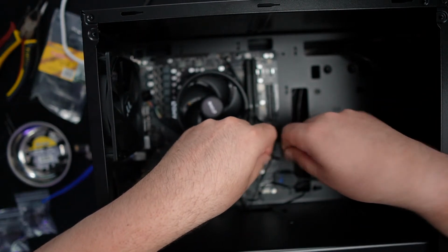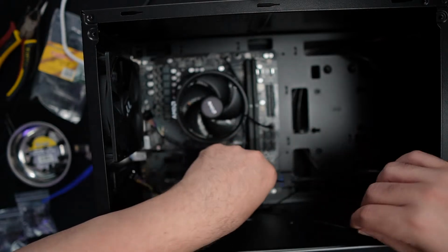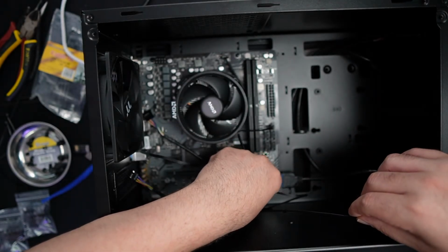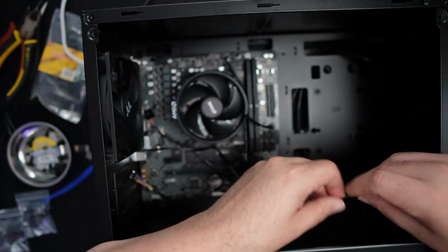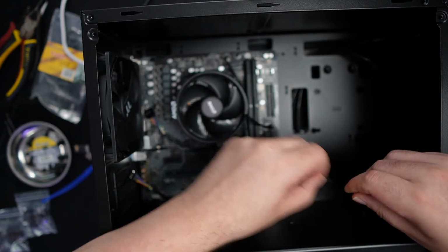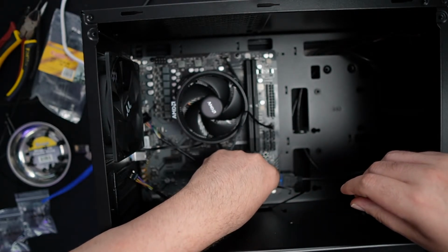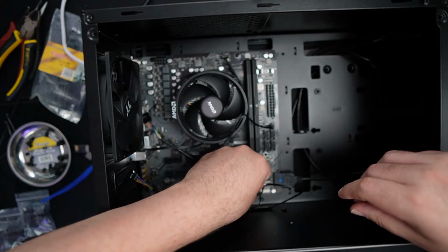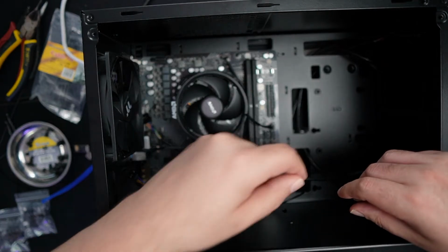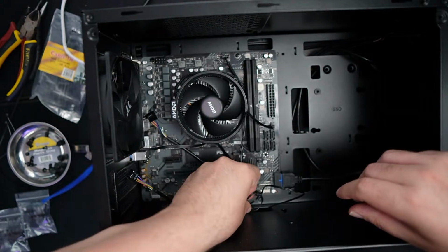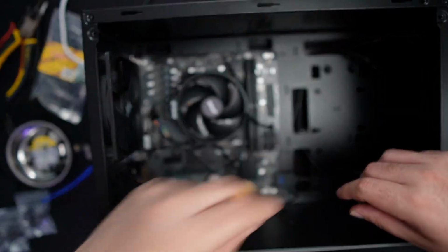But your hard drive light needs to match positive to positive, negative to negative. Same thing for your power light. Positive to positive, negative to negative. And if I could see what I'm doing, make sure I get that right. Yes, I do. Tuck that in there for now, just to get it out of my way.